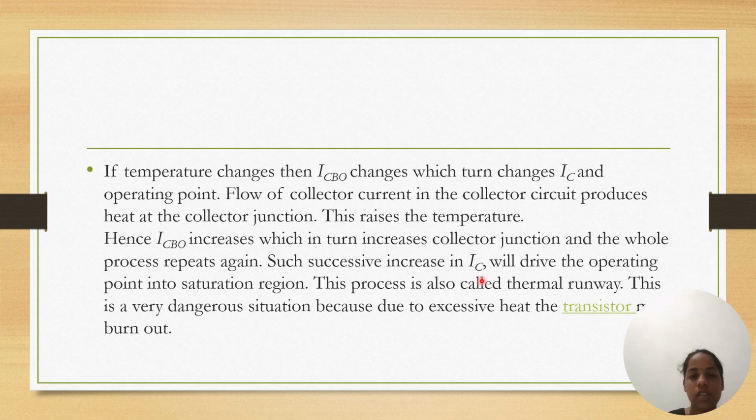Such successive increases in IC will drive the operating point into the saturation region. This process is called thermal runaway.